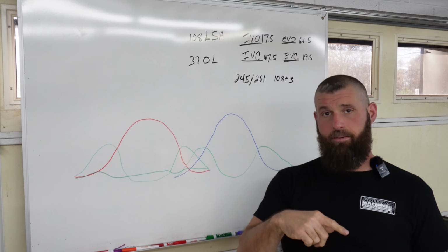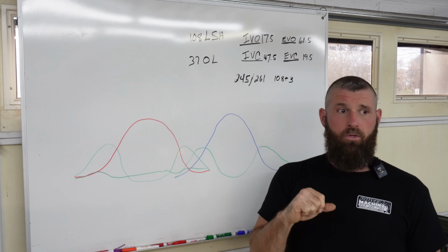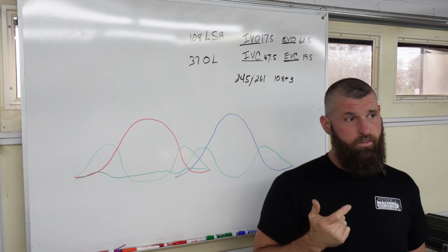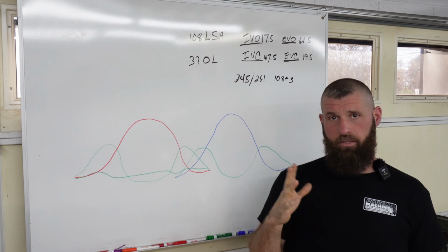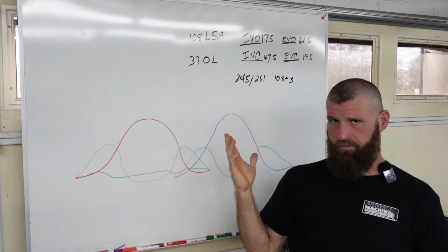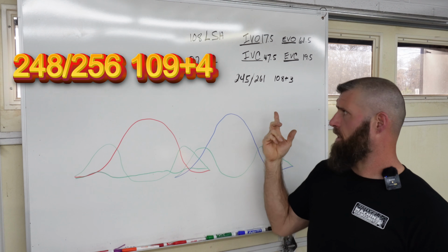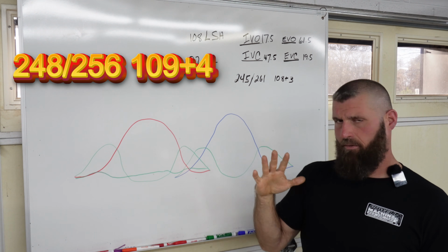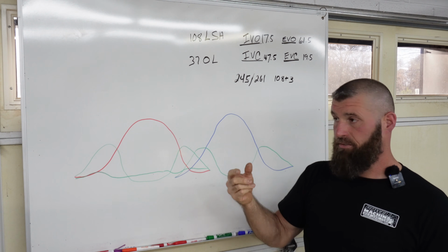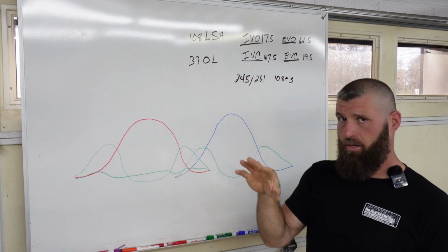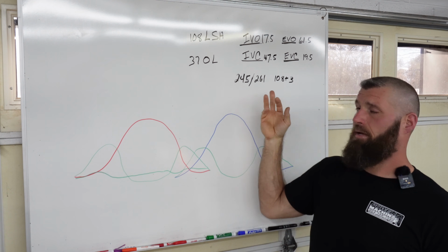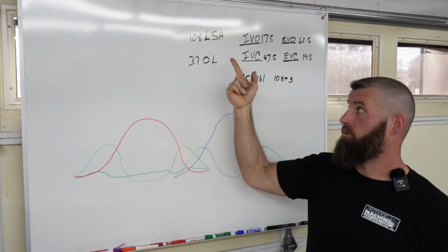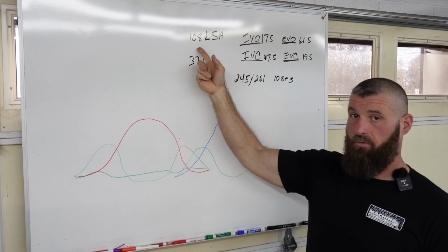The original cam they had was 248, 249. It was like two or 3 degrees difference, and the exhaust was 56 or 58. I don't remember. Gosh, I apologize. But that data is in the video. They go over both cam cards. So we had a few less degrees on the intake, a few more degrees on the exhaust, and was 1 degree tighter on the lobe separation,